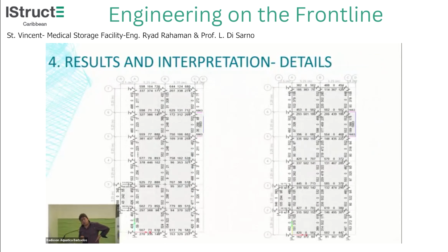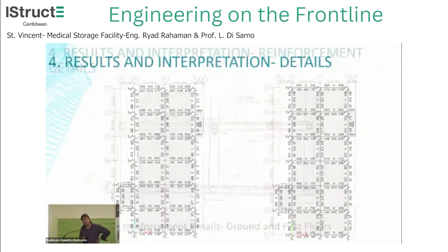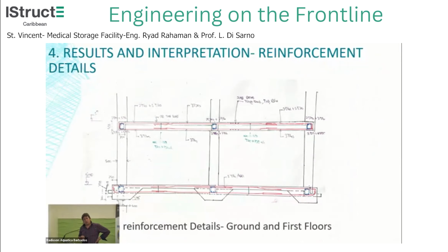You go back, right, the reinforcement, almost minimum. 880 kilonewtons over the junction, 500 just minimum everywhere else. On your beams, you should see what floors those are, first and second floor or something. Right, so the reinforcement details at ground level, what we have there, 2 T20s and 1 T16 at the bottom. That's the highest. Everywhere else, first floor, I think it's 3 T16s, 3 T16s, general spacing of shear links.